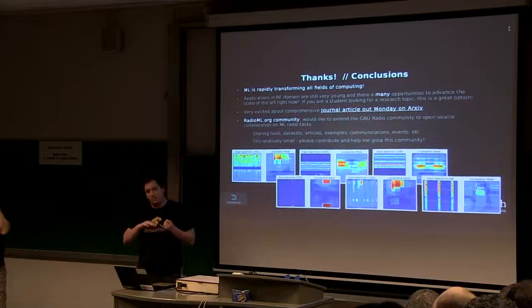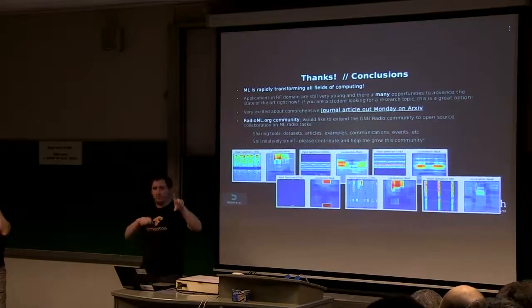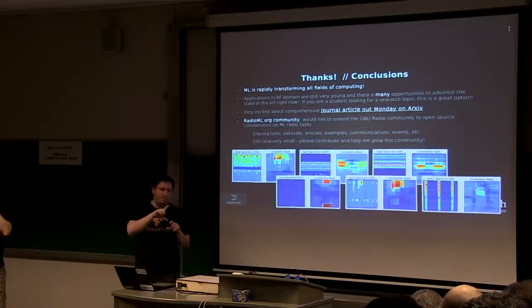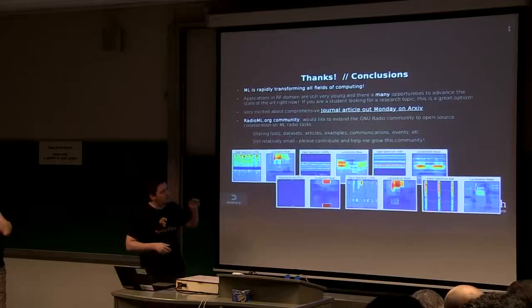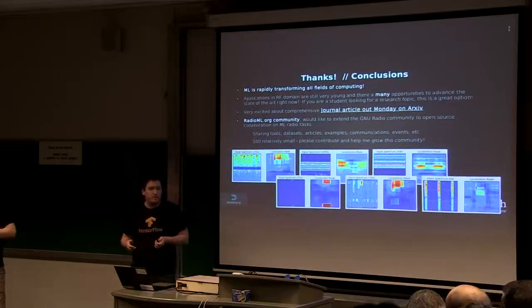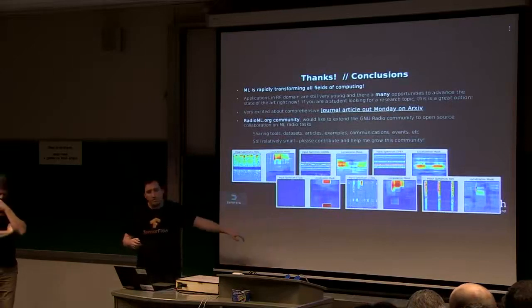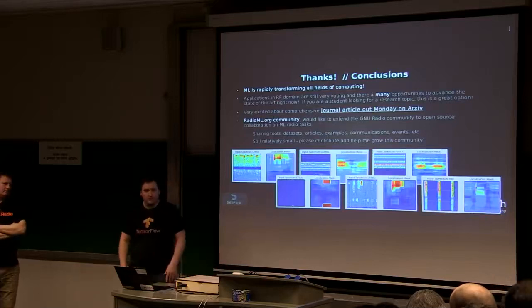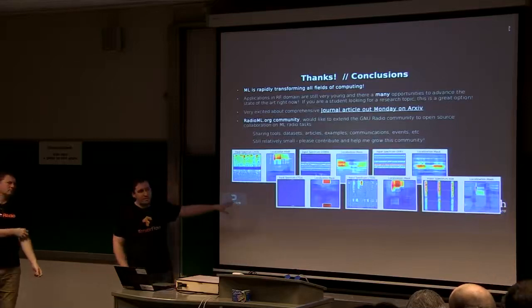You have n channels of 2D image coming in and m channels of 2D image going out, so you can use one-by-one filtering to reduce the number of channels. By playing tricks like that, we were able to drive the complexity down maybe 50x or so. So we're now a factor of about 4 lower in op counts than the classic approach in that application.